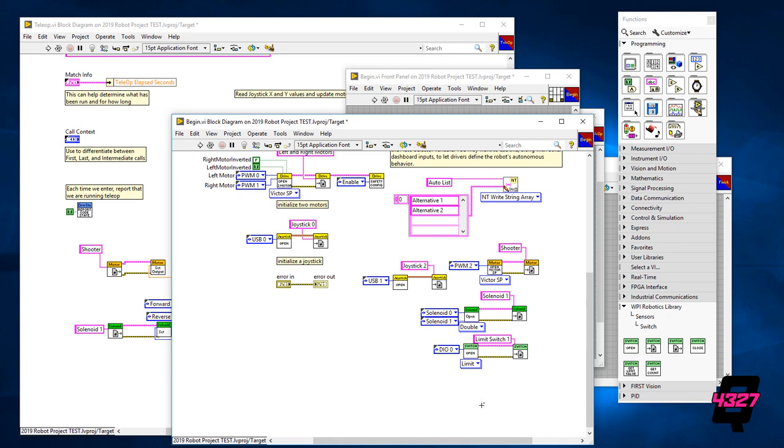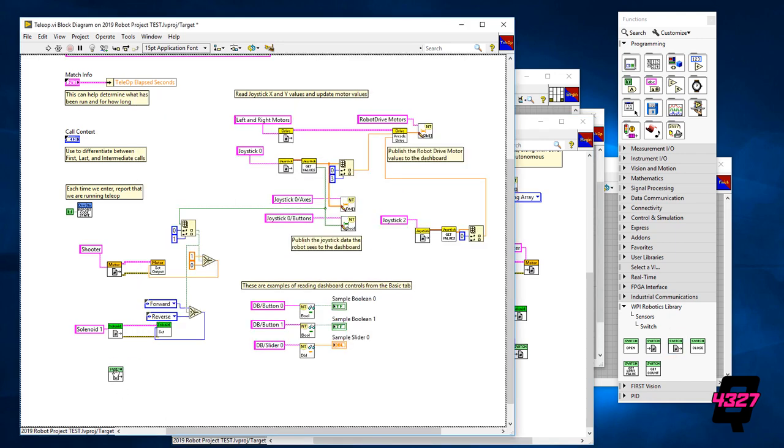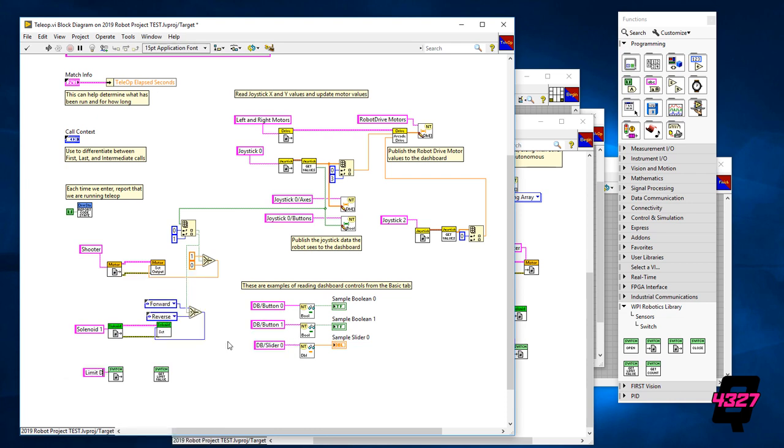Lastly, if you want to add a sensor or a limit switch, then it's very similar. At the begin VI, we will open and then leave that same arrow pointing to the numbered page, but for a switch. We will need to name the switch and tell the computer what DIO port, just like a PWM slot, to locate the information.